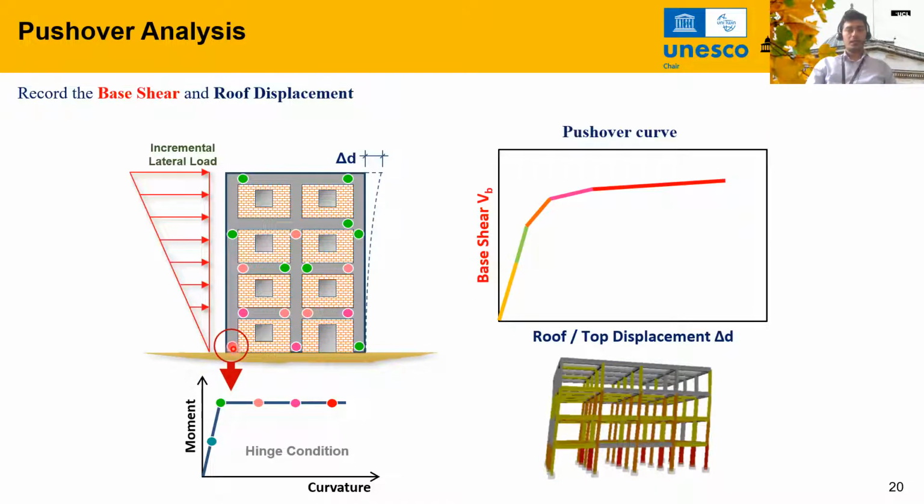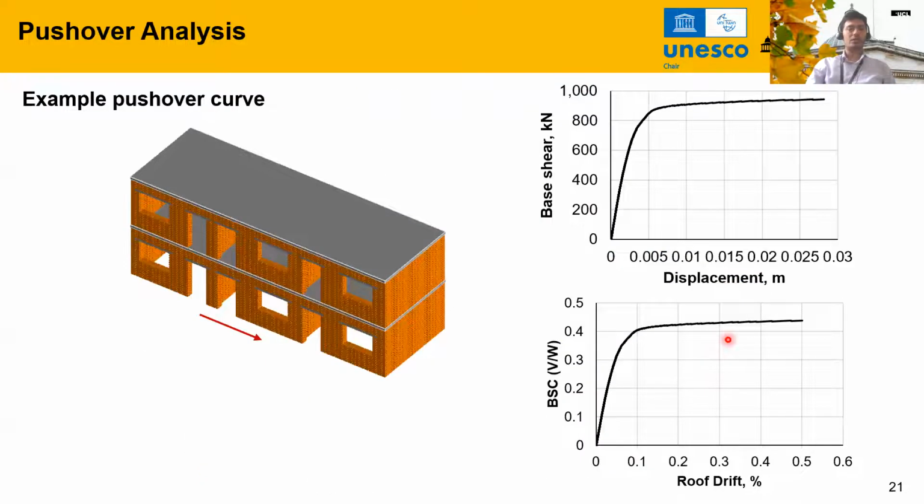Okay, then this is the ultimate stage where you can define your building has now collapsed, because so many of these beam columns have already gone into nonlinear inelastic range. So you can define this point. Okay, this is my collapse state. So that's how you conduct Pushover analysis.